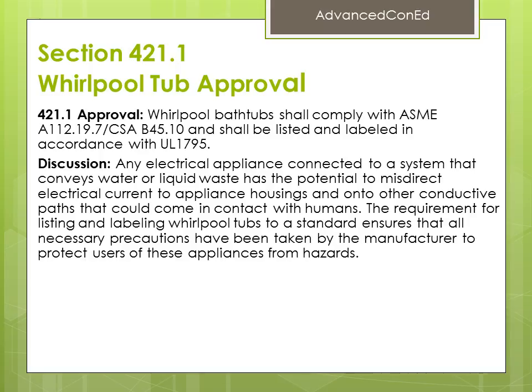Section 421.1 Whirlpool Tub Approval. 421.1 Approval. Whirlpool bathtubs shall comply with ASME A112.19.7, CSA B45.10, and shall be listed and labeled in accordance with UL 1795.